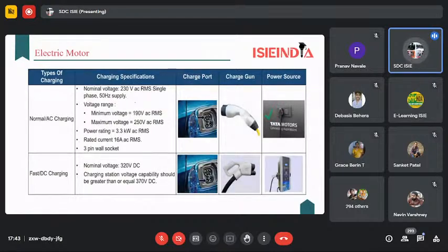So if you are choosing, level 2 is the best one, because you are investing 10 to 20 lakhs in a car, and it may not last after 3 to 4 years. If you go towards the maintenance part, that is not good. So for that, we have to prefer the level 2 charger, or you can move toward fast charging facilities also. But as per your requirement, if you have time, I suggest going with level 2 chargers.